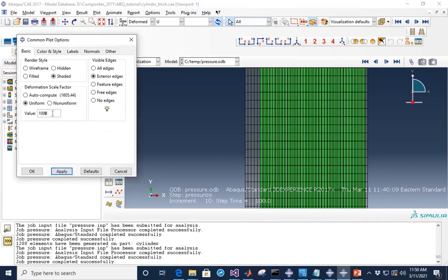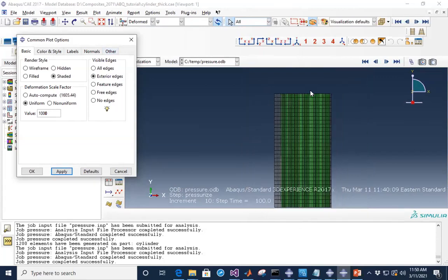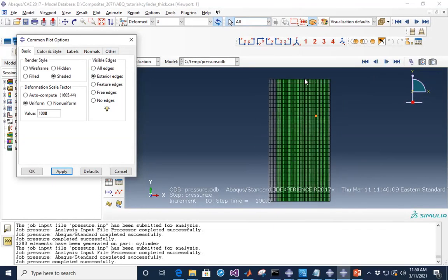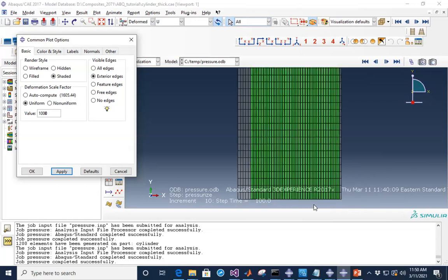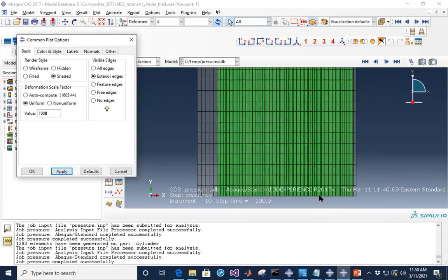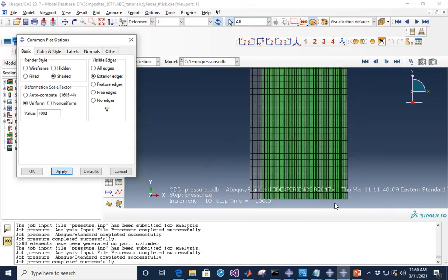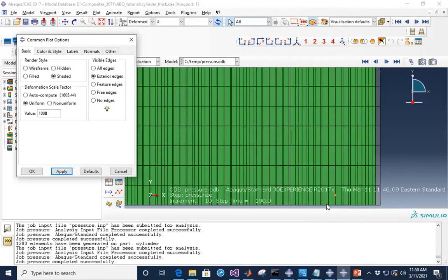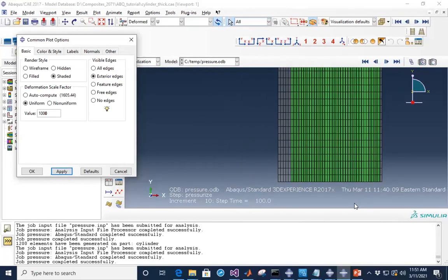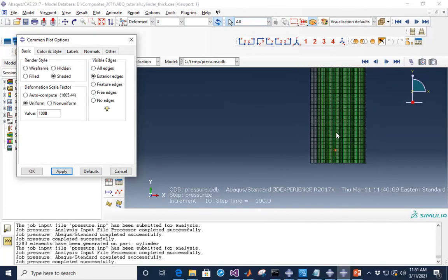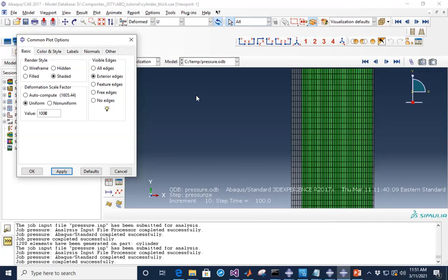However, now let me zoom out slightly, and then we can see what's happening at the top, because we impose the plane strain conditions, irrespective of how much we are blowing up our deformations by. You see, because we have set it to 0, irrespective of how much we magnify it, that displacement is going to be 0. So the bottom and the top edges in the deformed specimen are still at the same vertical level as the undeformed specimen. Okay, so that's another useful trick in Abaqus.